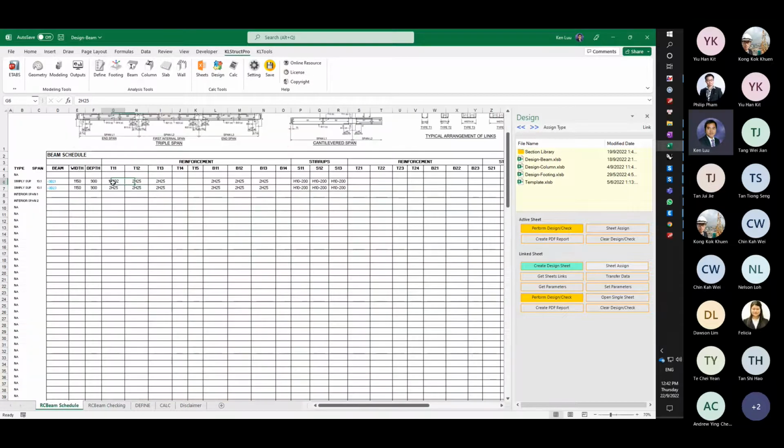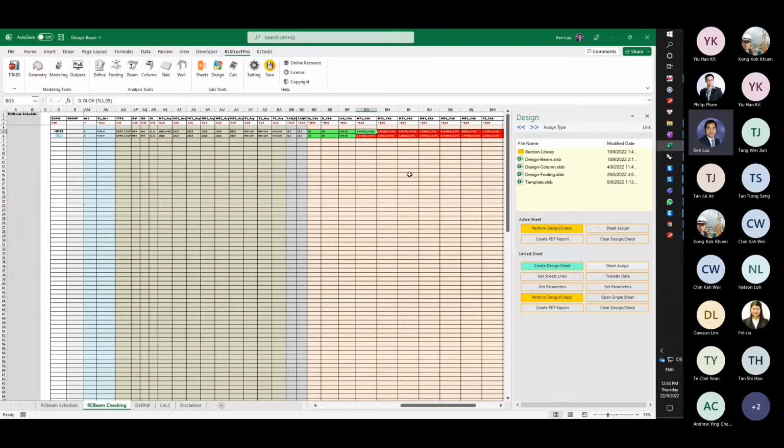So here you come back and increase the reinforcement. The program is designed for any kind of added reinforcement as you want. You can either put in one row, one number like this, or if you want to add reinforcement, let's say for H32, something like this, the program also understands it and performs the check. You see, it shows that 4H32 is added, and the reinforcement increased to 1.09, and then the UR is 74.